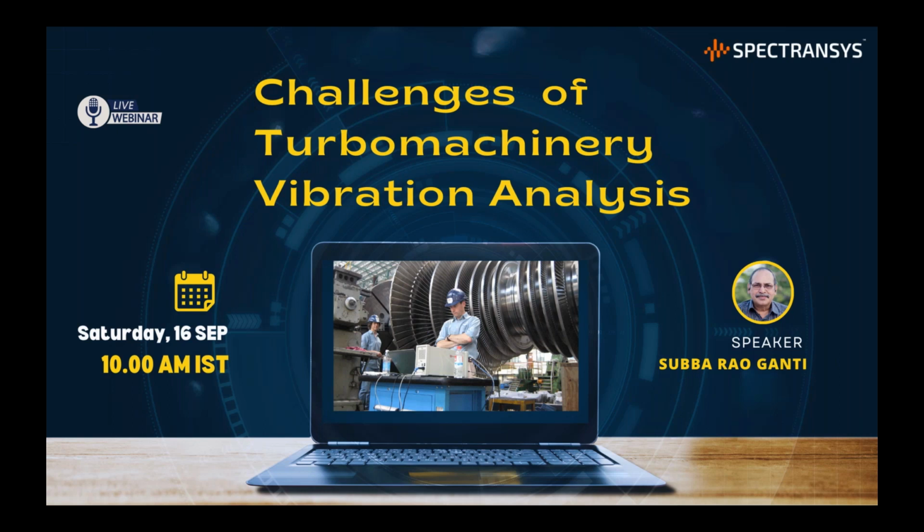But otherwise, for the other industries like power stations or other applications, what you basically need to do is ask the OEM for the general rotor dynamic analysis, and then try to get it vetted. If you have enough knowledge to evaluate their document, it's fine. You yourself can evaluate and find out how the calculations were carried out for that particular machine. Otherwise, you can hire a consultant who has adequate knowledge in rotor dynamics, and they can help you understand the authenticity of the document presented. That's what comes to my mind to answer your question.